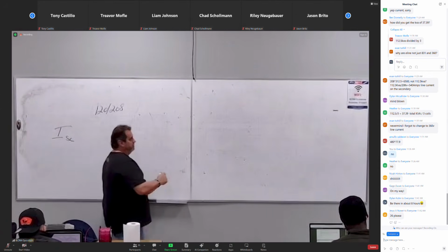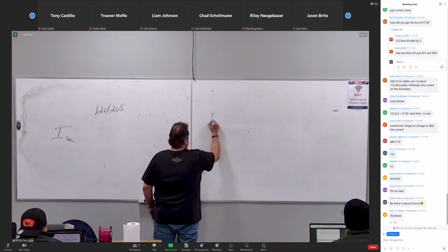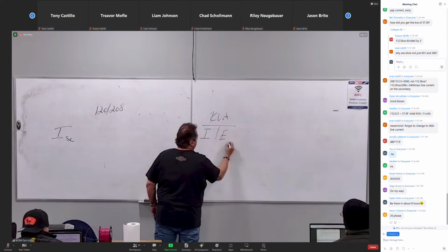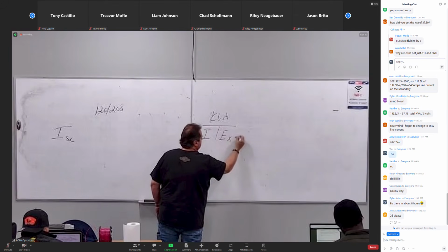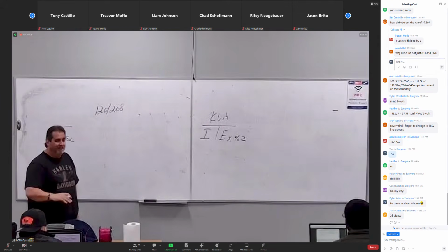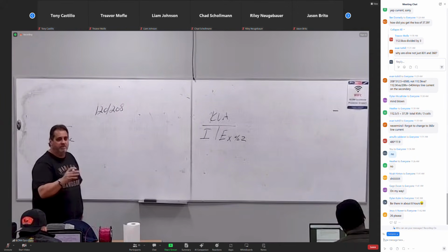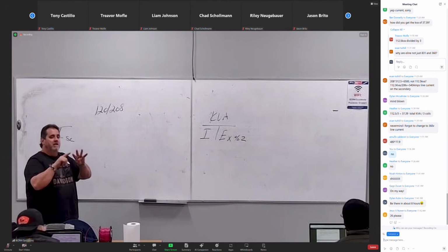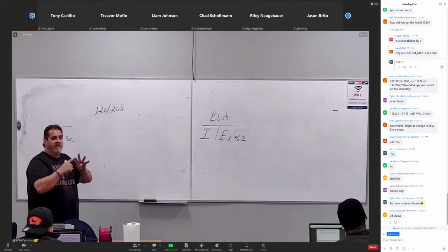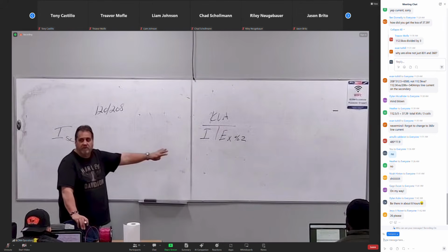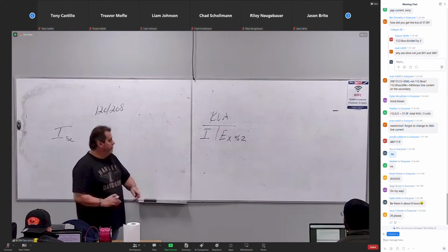Once again, with transformers, nothing changes, except here we have to multiply this by the percent of Z. And we just take straight voltage. We don't have to do 831. We don't have to do 1.732. We just take the 208 because it's between phase to phase. It's not between A phase, B phase, and C phase. It's A and C phase that had a fault. Does that make sense? It makes it single phase. So people say, let's say 3-phase panel though, shouldn't that be 1.732? Not when you're solving short circuit. All you're doing is this.